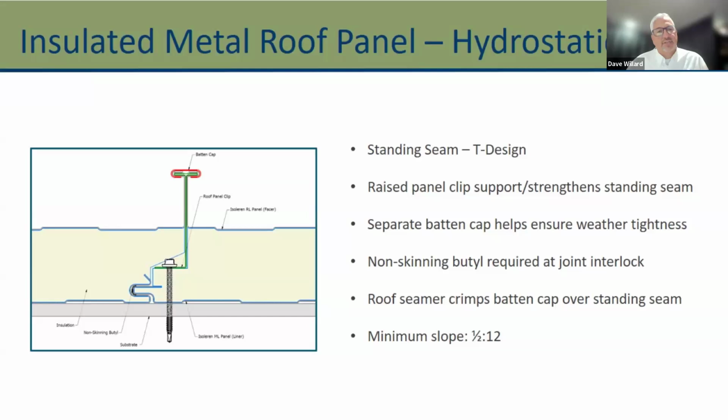And again, this is an insulated metal panel, so you have steel on both sides with a polyisocyanurate core, which can give you about an R-8 value per inch. So a 6-inch panel essentially can get you about an R-48 for a roof panel. Now your roof is done, you're dried in, and you have a nice clean look at the bottom if you're over purlins, and the top just looks like a nice standing seam roof.